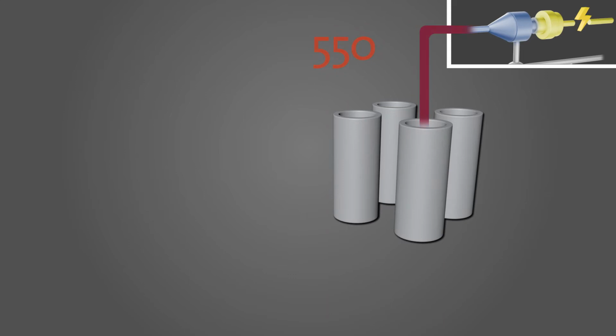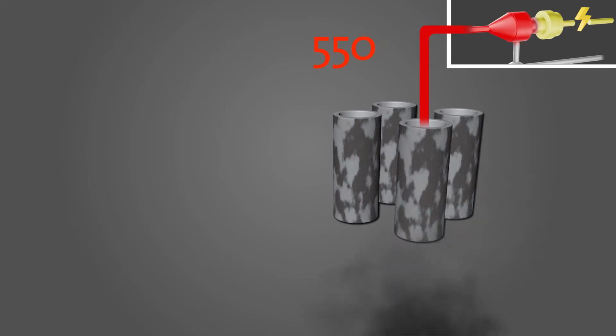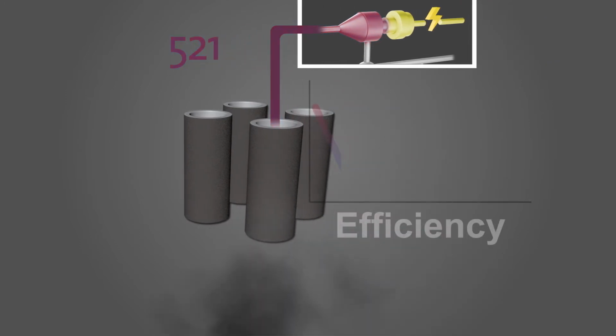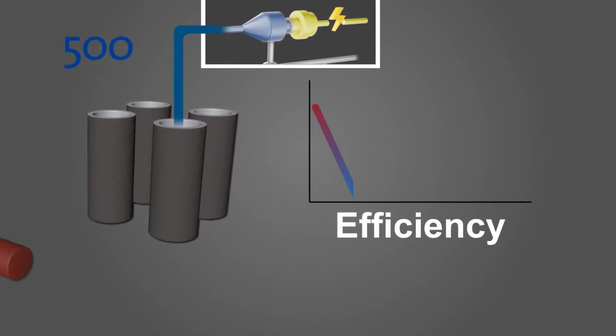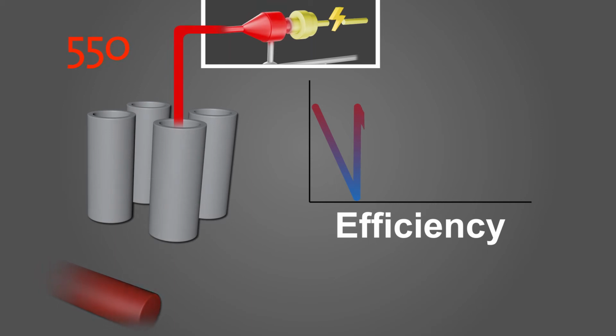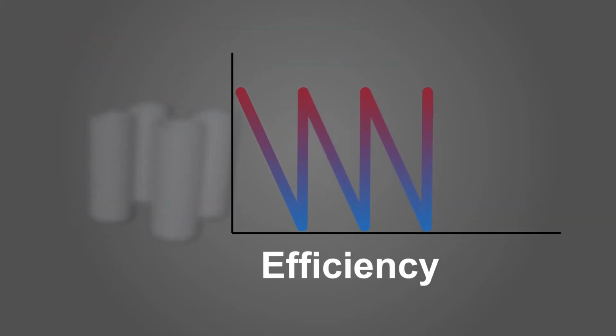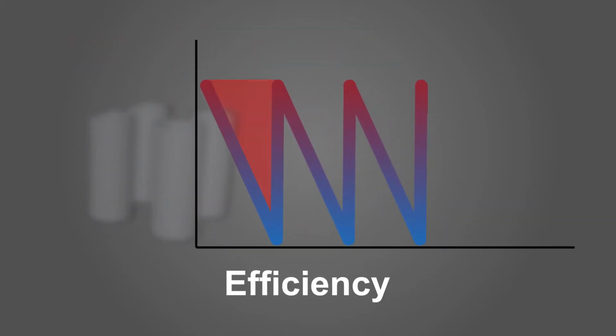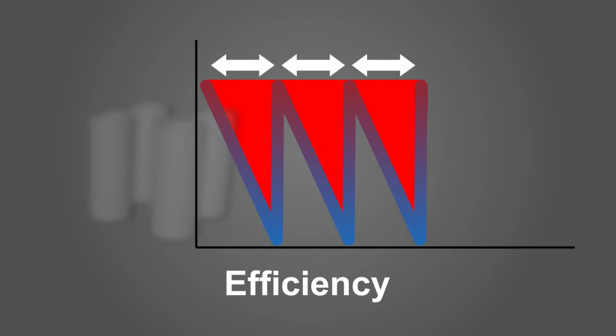Clean surfaces give high steam temperatures and high steam production. As the fouling increases, steam production and the important steam temperature drops. To restore the heat exchange, the surfaces are cleaned with high-pressure steam. This steam soot blowing is performed regularly, normally between 2 to 3 times per day. The fouling causes losses, depending on fouling rate and the intervals between steam soot blowing.